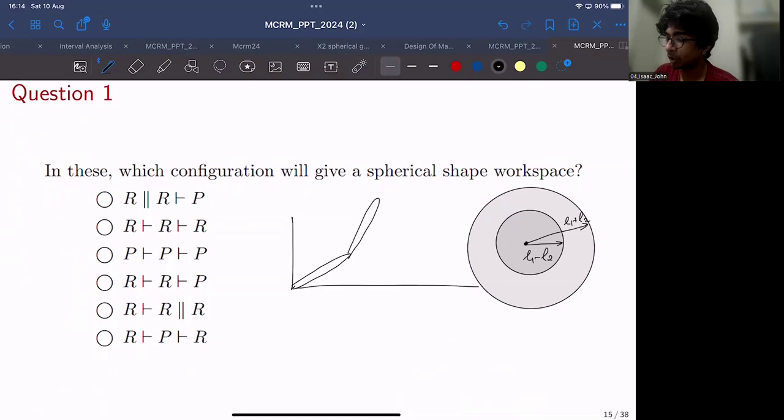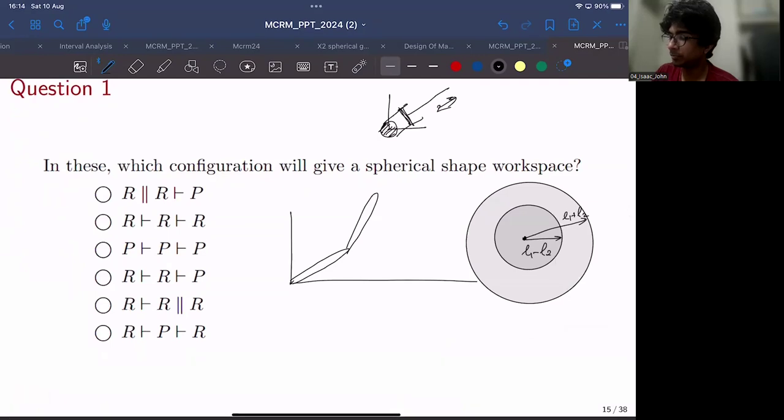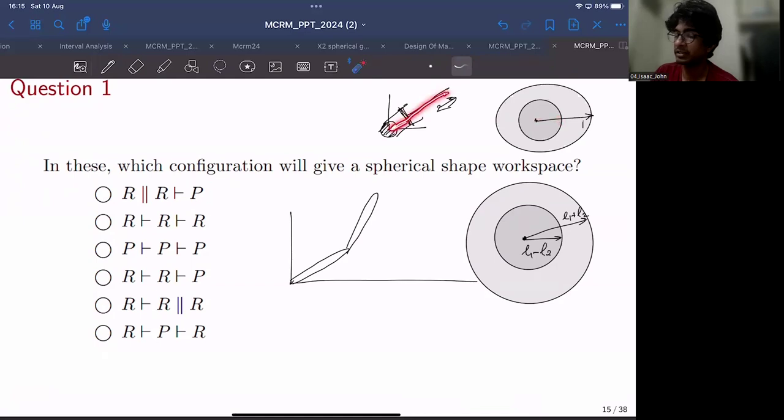And we have also seen an RP robot like this. One link would rotate like this. Another link would be a prismatic joint that can move back and forth. So in this case also, it can reach any point in this XY space. It will also be a circle like this. So the maximum radius of the circle would be the maximum length at which the piston is extending, and the minimum radius would be the minimum length at which the piston is contracting.